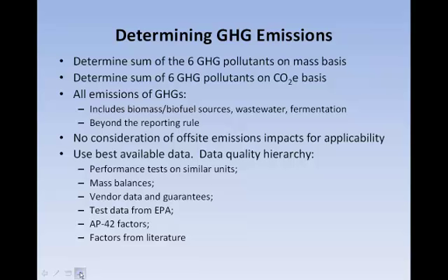As with any emissions analysis, one must use the best available data to determine the emissions. The data quality hierarchy is for all pollutants. Generally, the more unit-specific the emissions data, the better. And this would include possibly performance tests on similar units, mass balances, vendor data and guarantees, test data from EPA, AP42 factors that are put together by EPA, and factors from various literature.